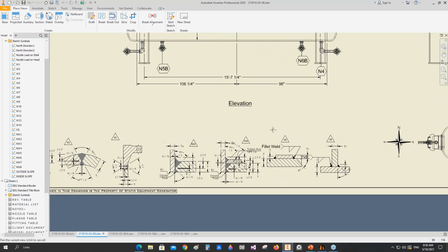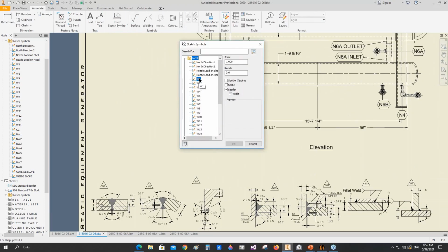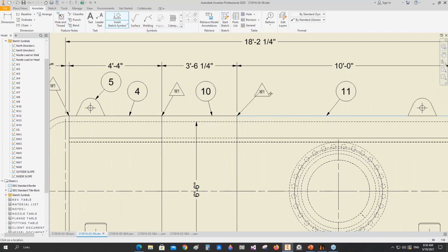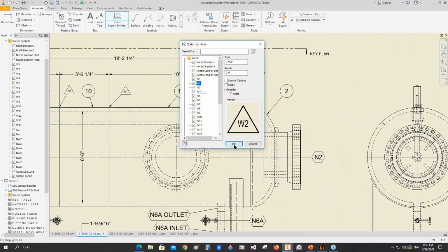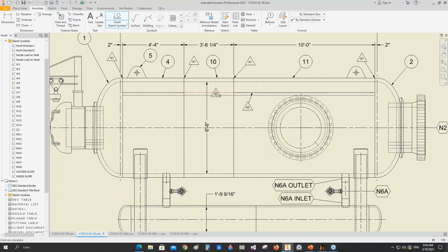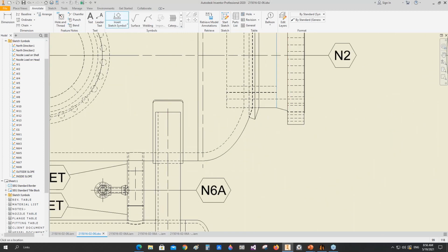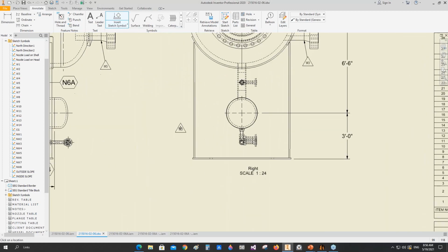Now to update that on the drawing, from the insert tab, we will define the welding line details like this, and let's select to define the longitudinal welding line orientation. Okay, C for the welding flanges, like this one and that one.